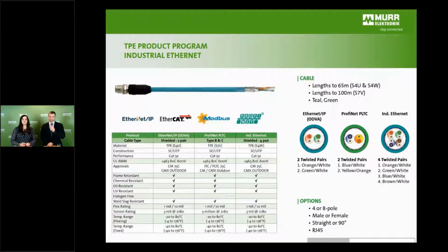Excellent. Okay. So what you can see here is the Industrial Ethernet cable. This one is in gauge 22, and it also has the PLTC rating on the cable. That means you can also go with this cable into a tray. For the Ethernet IP versions, it's not allowed because of the cross section. It's too small. But those cables are also listed cables, which makes it easier for the UL inspector. Definitely, good.